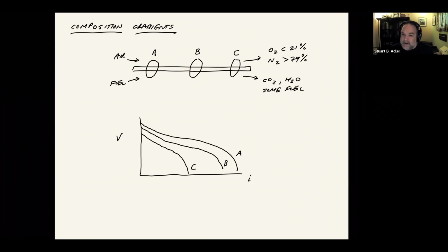Okay, so now imagine this were the case. We measured them, maybe not 3, we measured many, many different polarization curves for all the different possible gas concentrations that you have in the stack. And we theorize that this cell in our stack behaves the same way as these individual cells that we just tested with the uniform composition. If that's true, then if we pick a particular operating voltage, let's say I pick right here,